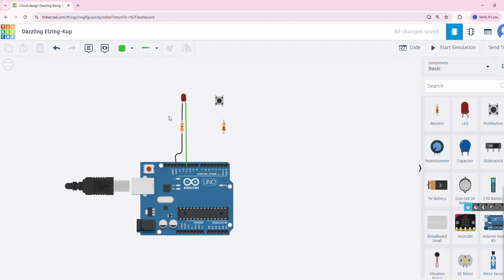At the same time, we are going to make connections for the push button component. Again, the second resistor's terminal 1 goes to the board ground. Then the resistor's terminal 2 we connect to push button terminal 2A.